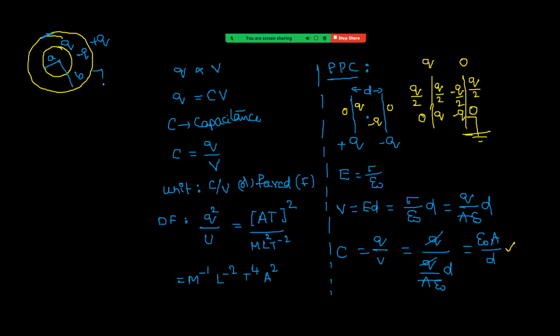So when we are grounding this one, then on the outer face, charge becomes zero. That means now the field is only in this region. Means energy is confined to only this region. So potential energy will be stored only in this volume. Okay. I can say calculation of capacitance C equal to Q by V. Q already we have taken. Now we want, between these two, what is the potential difference?